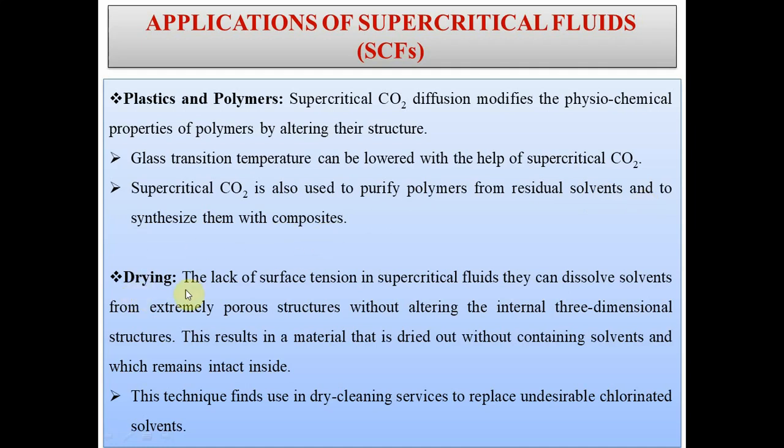Drying industry. Due to the lack of surface tension in supercritical fluids, they can remove solvents from extremely porous structures without altering the internal three-dimensional structures. This results in a material that is dried without containing solvent and which remains intact inside. This technique is used in dry cleaning services to replace undesirable chlorinated solvents.